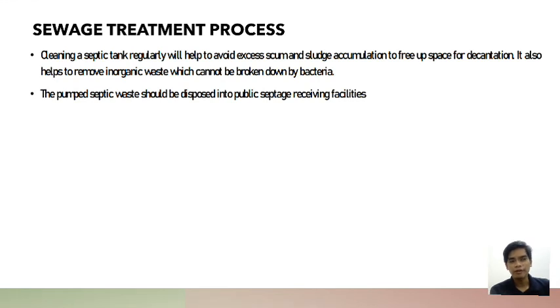Cleaning a septic tank regularly will help to avoid excess scum and sludge accumulation to free up space for decantation. It also helps to remove organic waste which cannot be broken down by bacteria. The pumped septic waste should be disposed into the public septage receiving facilities.